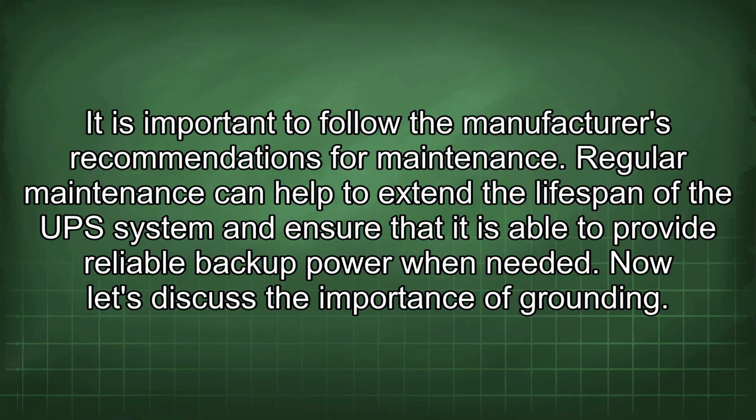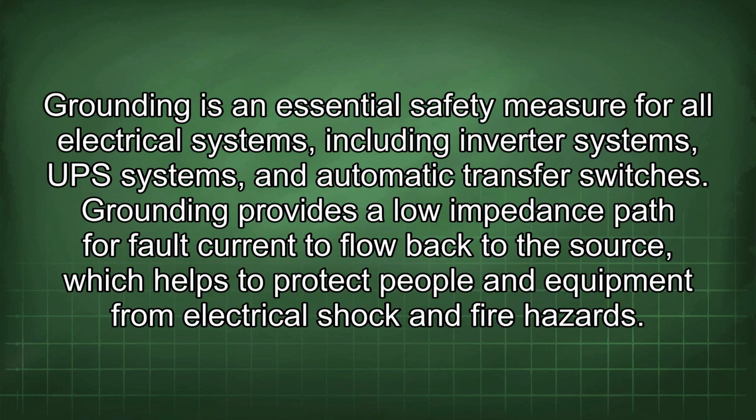Now let's discuss the importance of grounding. Grounding is an essential safety measure for all electrical systems, including inverter systems, UPS systems, and automatic transfer switches. Grounding provides a low impedance path for fault current to flow back to the source, which helps to protect people and equipment from electrical shock and fire hazards.